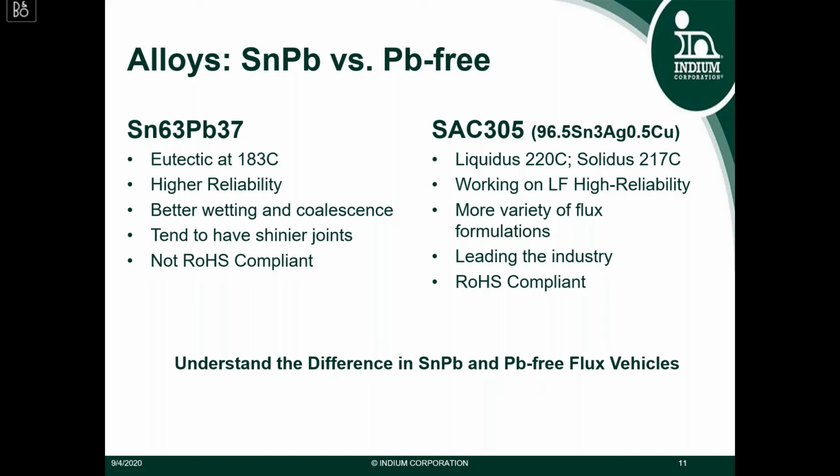SN63 for many, many years was the go-to solder alloy. It has excellent reliability. It's eutectic, which means that it has a liquidus and solidus that are equal. It melts and solidifies all at the same temperature, in this case 183 degrees Celsius. It has excellent wetting and coalescence, very shiny solder joints.